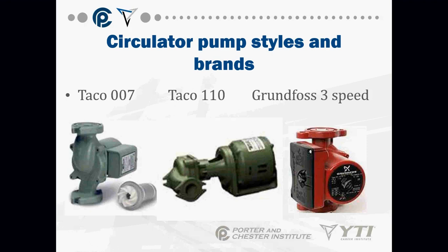So here you've got a couple of different styles. The Taco 007 is very, very common in residential and light commercial applications. This type of circulator is what we call a wet rotor circulator, which basically means that we are using the water inside the boiler to lubricate the bearings inside the pump. These types of circulators are serviceable in the field. This device right here is your circulator component, which does all the circulation of it.